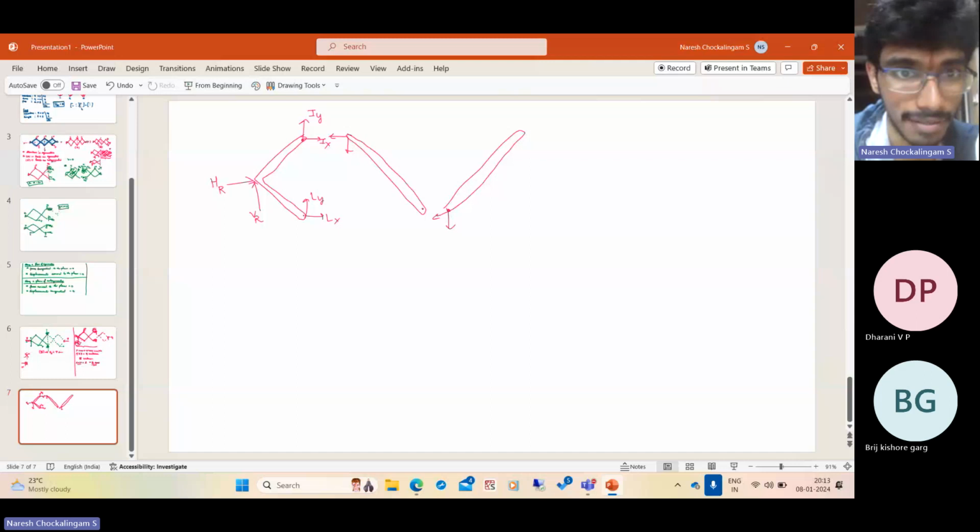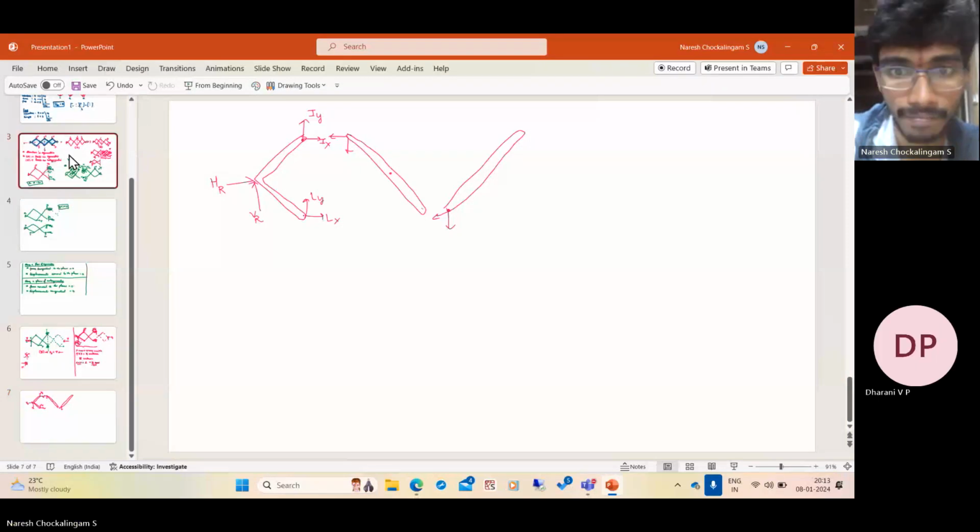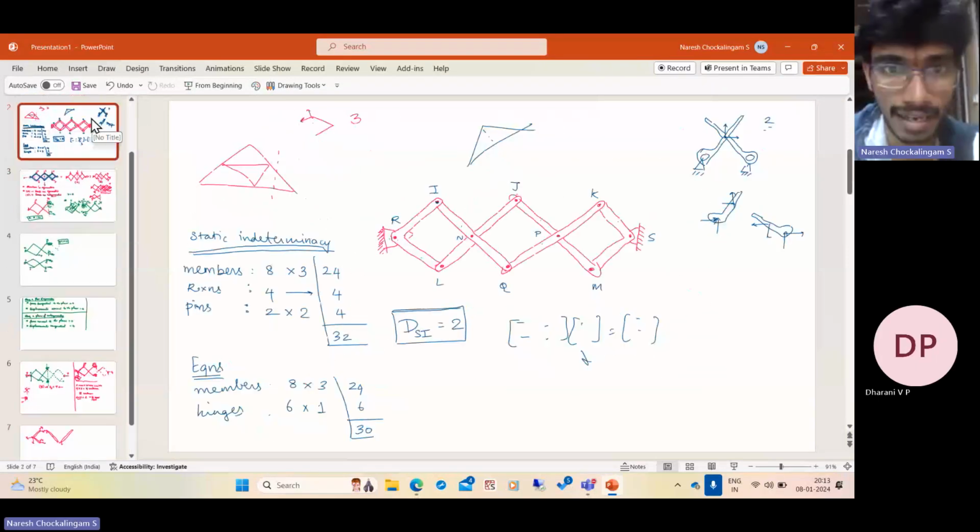Here, at this point, we have the pin forces. And this pin is N. So these pin forces are NX, NY. And here you have the pin forces, equal and opposite, so I am not listing them. So this point and this point are two points lying along the lines of symmetry. We know the horizontal force.